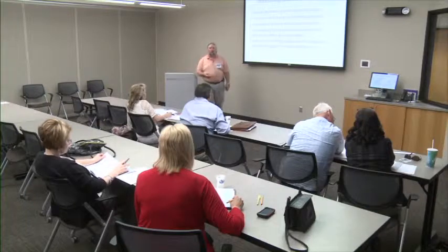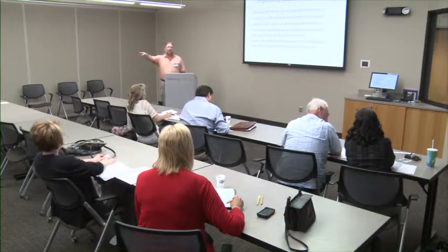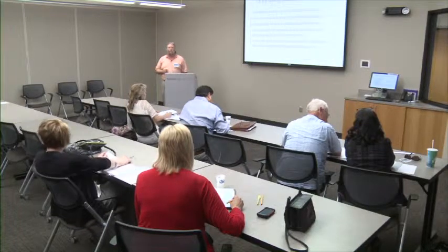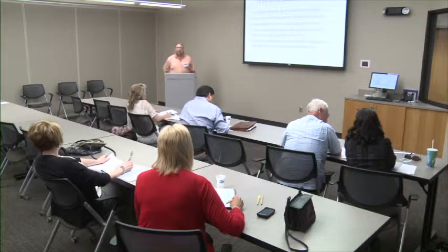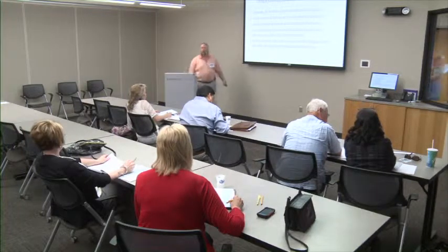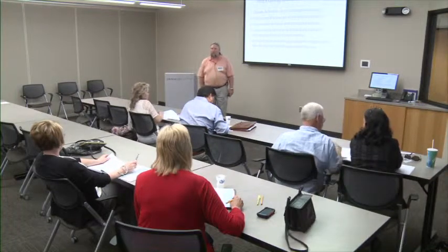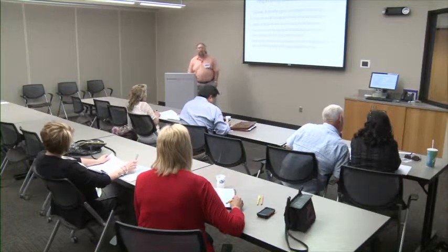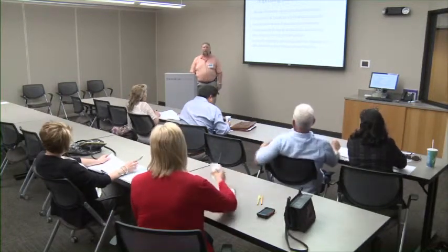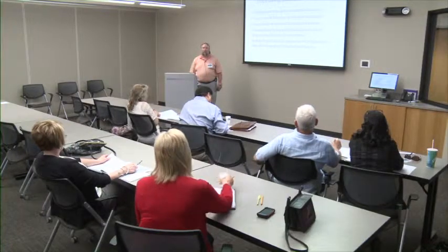Okay? Bring the people that are responsible for doing the work into your scheduling process. Don't assume that you know how many days it's going to take him to do the work. Ask him. Okay? How many days is it going to take you to lay the sod? Because I've got 5 days in the program, and it's 100,000 yards of sod. Can you do it in 5 days? Yes or no? They're going to know that. Or, you know, I put 1 day in there for seeding, but it takes me 3 days just to prep.